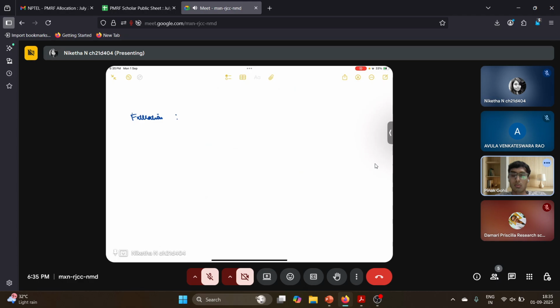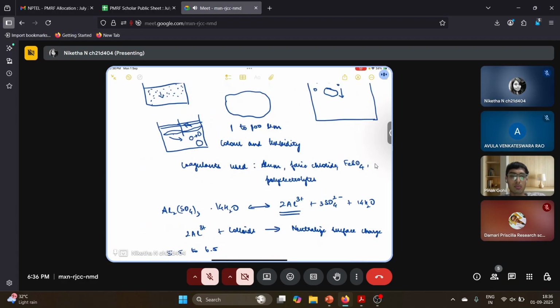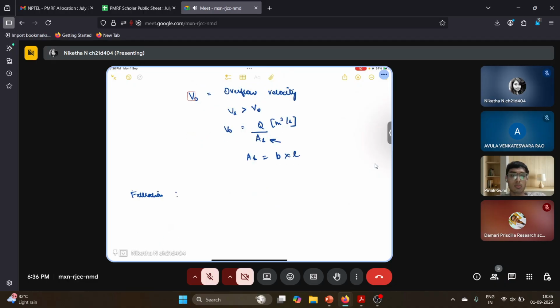Soluble solid. What? Soluble solid. I didn't get you. Settleable solids. If solids were settleable, then why will we go for filtration? We could have just gone for a sedimentation tank or maybe for coagulation or flocculation, right? Floating particles. I just said that screening is used for removing floating particles.